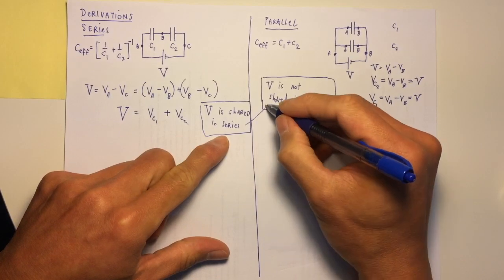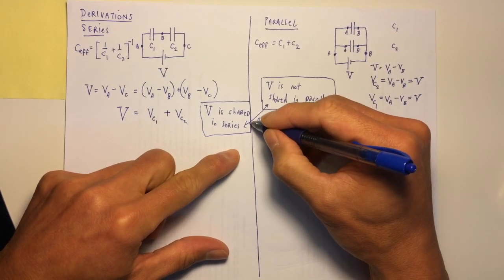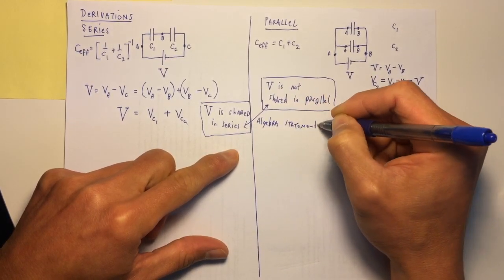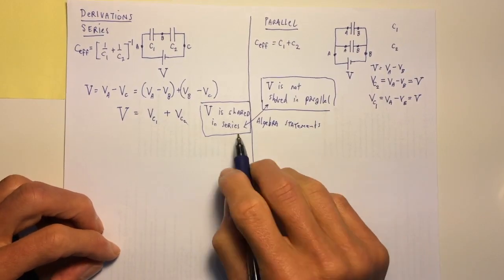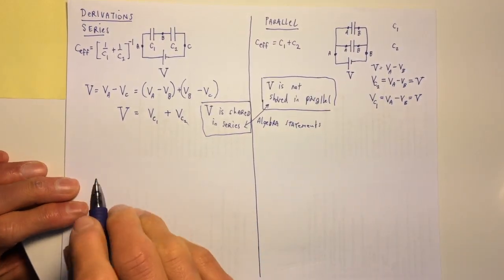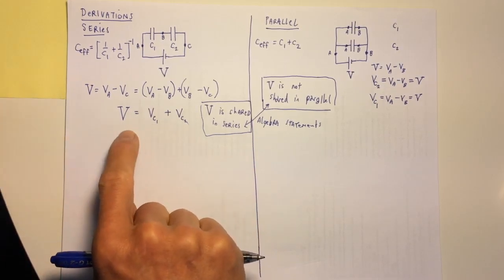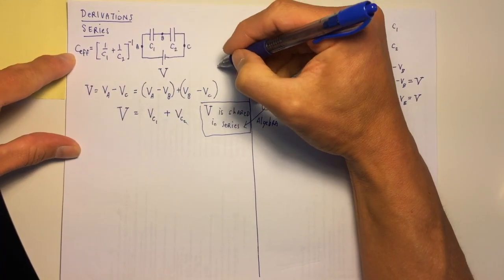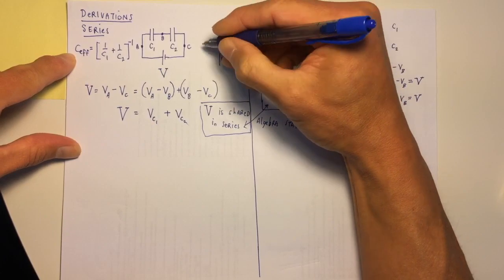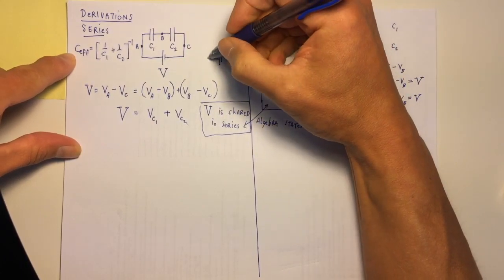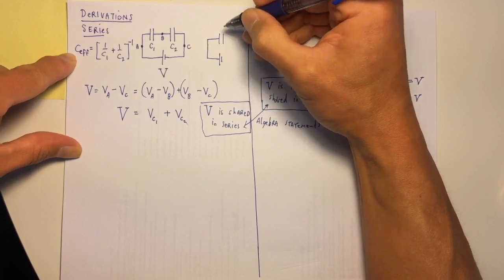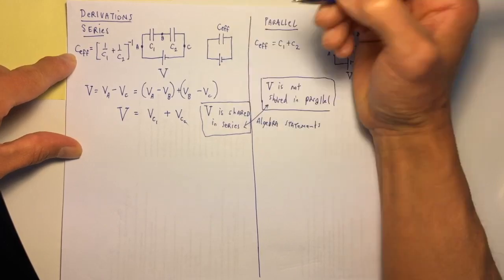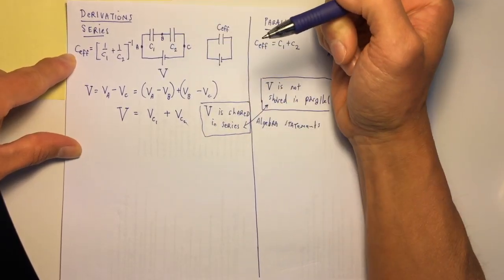These two things right here will always lead you to algebra statements for problem solving. Okay, so now when I want to draw an effective capacitance, what I'm trying to say is I would like to think of these two capacitors in series as actually just one capacitor that happens to have the same effective capacitance as the two capacitors in series in this case.